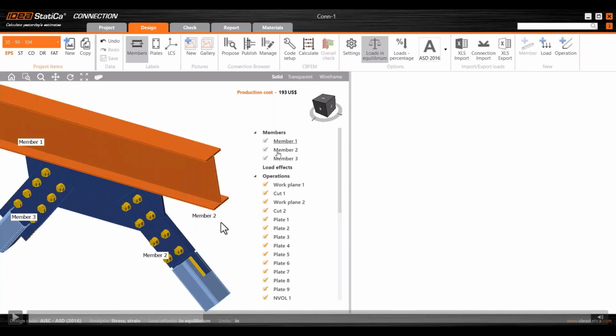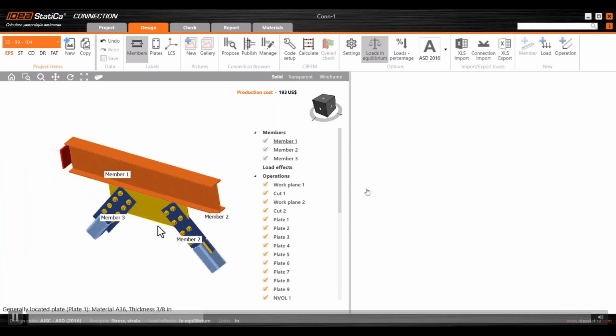Load effects, we don't have load effects, as you can see here. Why? Because that Revit model doesn't have any load. If there is a case where you transfer the loads from other software, let's say Robot or other software that you can transfer loads to Revit, you can bring those, but only if you have the information there in Revit. Also, I think we have an article on our site about that option, when the loads from Revit are transferred.